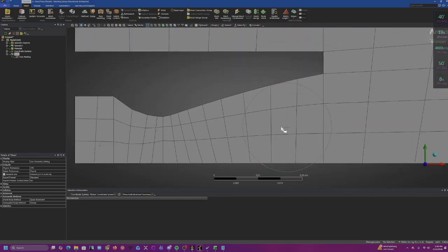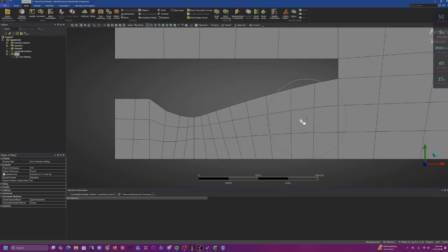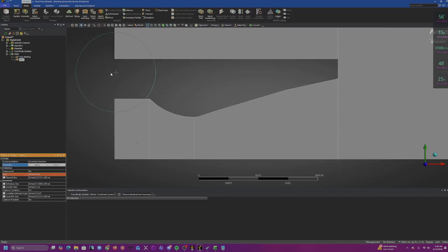All right, first we're going to be meshing our nozzle section. We're going to be using sizings, biases, and divisions to mesh. So let's start with sizing. Click on sizing. Our first sizing is going to be these 4 vertical lines.